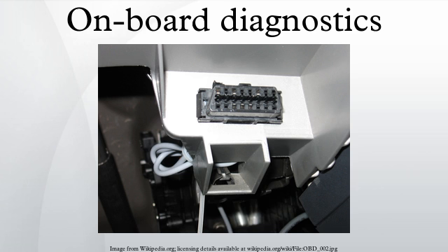The PID request and data retrieval system gives access to real-time performance data as well as flagged DTCs. For a list of generic OBDII DTCs suggested by the SAE, see Table of OBDII codes. Individual manufacturers often enhance the OBDII code set with additional proprietary DTCs.